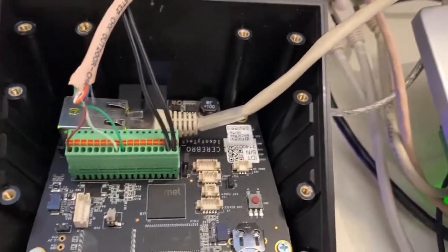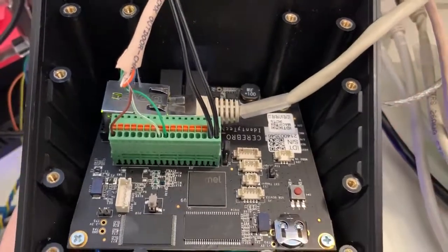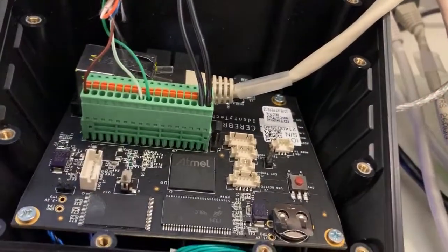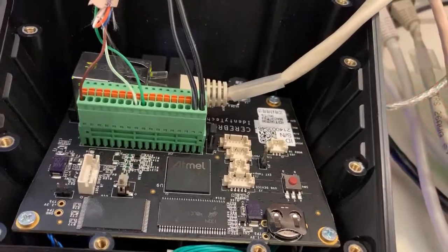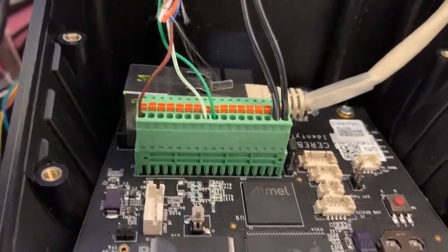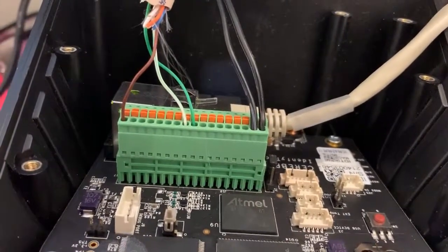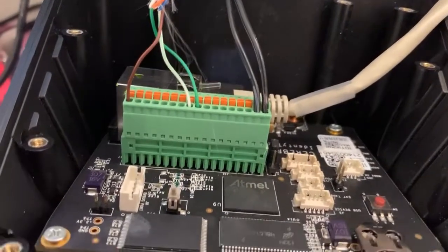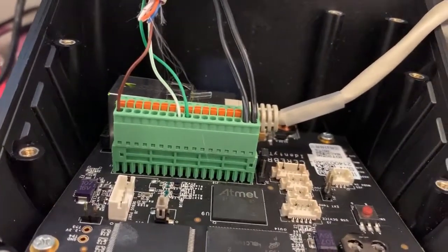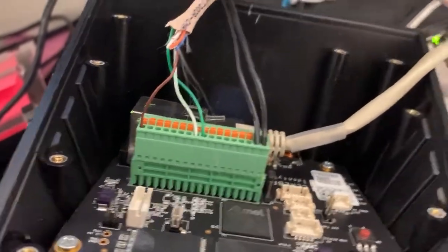have a patch cable and RJ45 cable running in to supply Ethernet connection, the LAN connection. We can see our two black wires are providing power, DC and ground. And then you can see over here to the left, we have our green, white, and brown wire. The green is going to be for data 0 out. The white wire is going to be for data 1 out. And then our ground wire is just our common ground connection that we used for Wiegand. So that's what it's going to look like on this side.